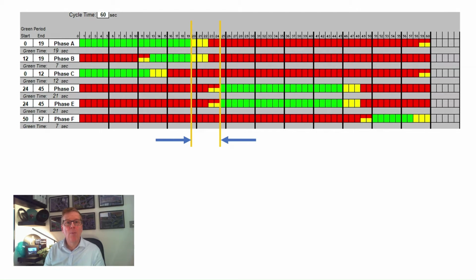By default, there will be a 5-second intergreen between conflicting phases caused by the leaving and starting amber periods, which are 3 and 2 seconds respectively. These are referred to as sequent ambers. We'll look at the issues associated with the intergreens from vehicular phases to pedestrian phases a bit further on.